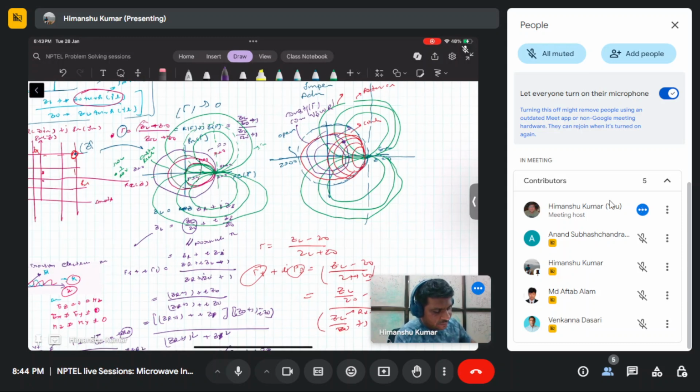Once you find this point on the Smith chart, taking the center, you can draw a circle, and where it intersects the line here corresponds to the reflection coefficient. So if you have any load, you can calculate the reflection coefficient, and if you know the complex reflection coefficient, then you can know the complex impedance also. This back and forth conversion is very easy in the Smith chart.